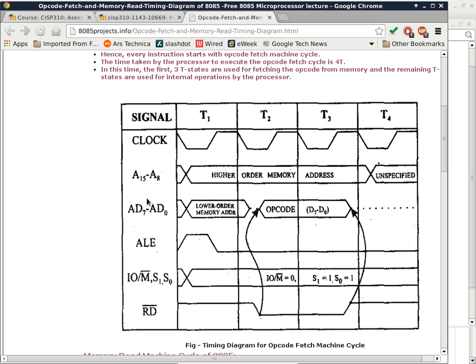Fiberglass cannot be processed by your body, okay? You breathe it in, it stays there. It just stays there. Okay, so you don't want to use a circular saw on these things. If you ever need to break one in half or into smaller portions, the way to do it is to score, and then you break it. Okay, that approach actually works.